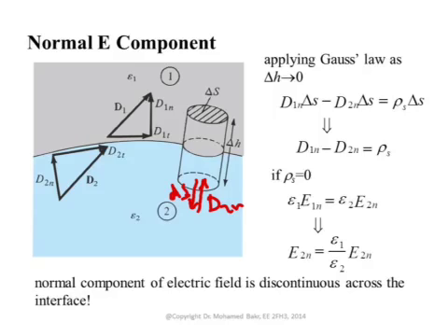This is what we have seen in one of the examples before in the lecture. If the field here is, say, 5 volt per meter, depending on the ratio of the dielectric constants, the electric field here may be, say, 7 volt per meter. Once you cross the boundary, there is a sudden change in the normal component of the electric field. Remember, the electric field has both a normal component and a tangential component. The tangential component is continuous. It does not see any change when you cross the boundary. The value just before the boundary is the value just after the boundary. The normal component of the electric field will see a big change.